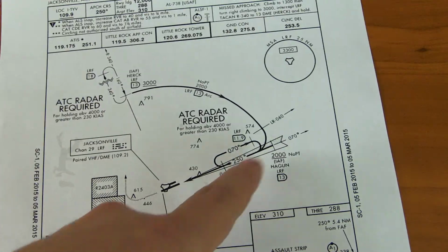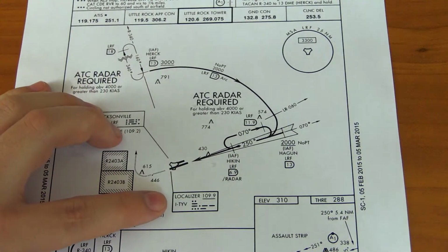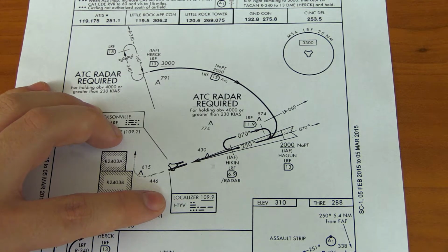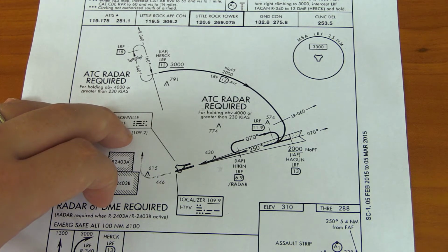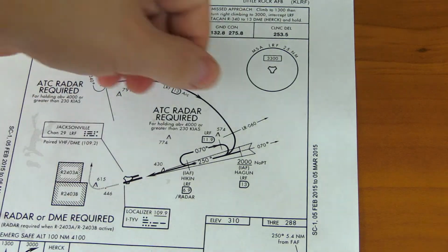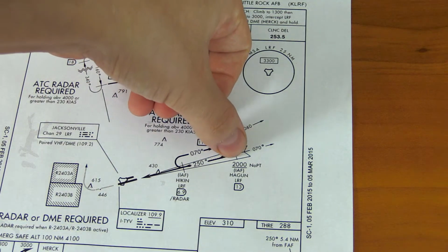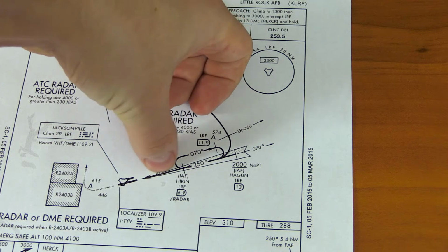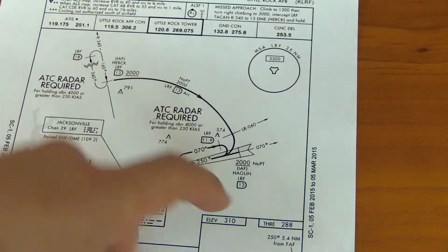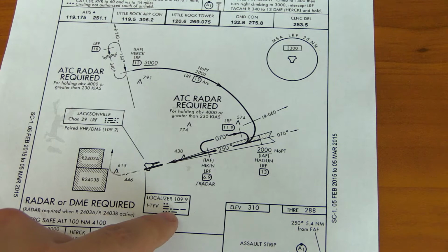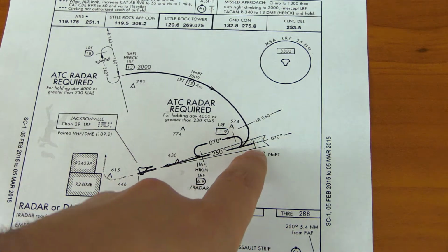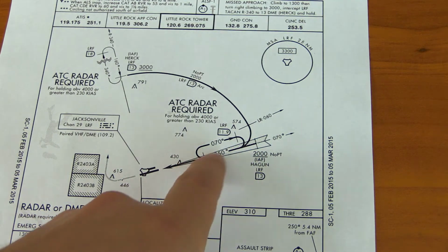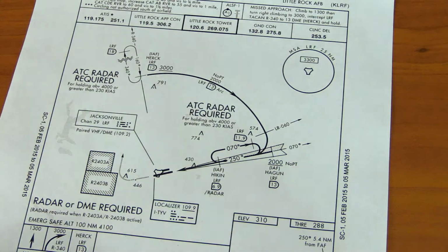You see here's the approach path, and at the end here we see a little note. It says Localizer 109.9, and that's megahertz. That's the frequency they dial in their nav receiver in the cockpit. So what you see here to the side is the Localizer path, it's called. And basically, if the airplane dials in this Localizer frequency in their navigation receiver, they're going to get guided down the center line of this Localizer here. And let's have a look at how that's done.